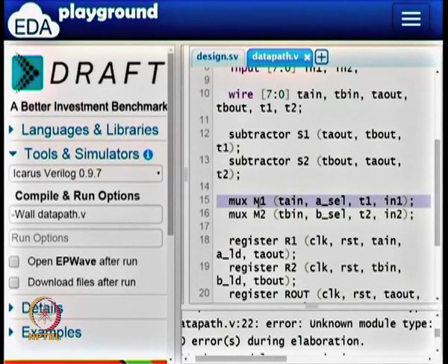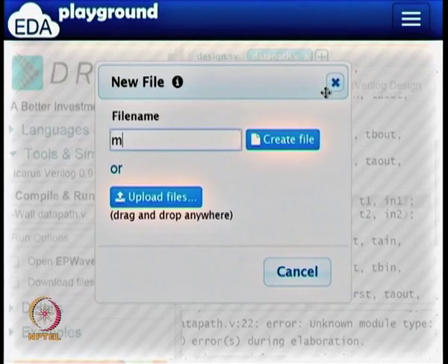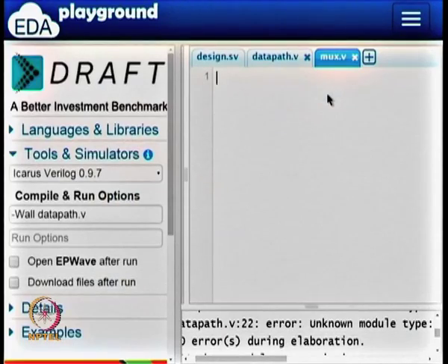I will cut and paste the design description that I need. Remember, for the multiplexer I said it is the output, select line, the 0 pin and the 1 pin. So these are the 4 things that I need. I am going to design something called mux.v. In mux.v, the module name is supposed to be mux. I did a cut and paste so that I know the exact order in which I am supposed to give things. The first one is supposed to be the output, so I can just call it out. The next is the select line, I will call that SEL. Then the input on pin 0 and the input on pin 1.